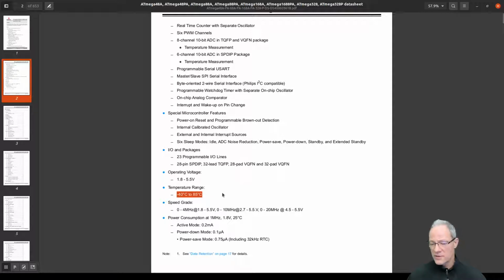So for example, there's a temperature range. If we want to use our smart device somewhere outside, then we have to consider how cold or how hot can it become before it becomes unstable. This doesn't seem to be a concern in a typical environment where people live. But if you want something extreme, let's say if you want to go to Antarctica where you could hit minus 50 degrees, or even create something for satellites, then you have to think twice if you're going to use this chip, or you need to look for a different one.